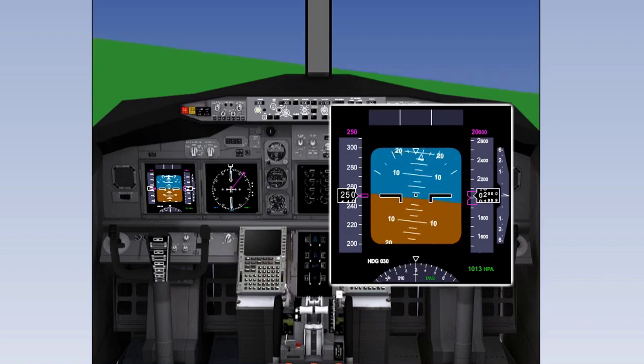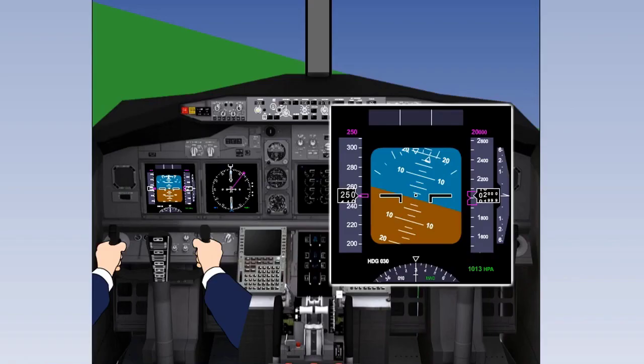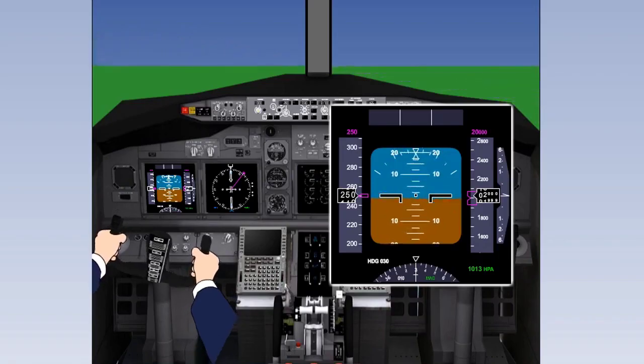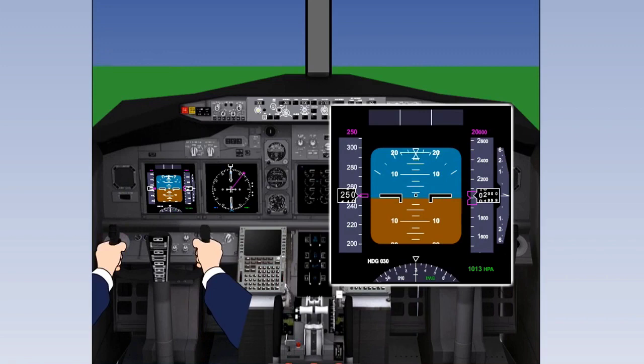In the event that a gust displaces the right wing upwards, the change in attitude will be noticed by you. By looking at your reference value, you will be able to mentally assess the rate and magnitude of the displacement. That will then allow you to mentally calculate the correction required to bring the aircraft back to wings level, and apply that correction to the controls. Having made the correction, you can see the aeroplane moving back towards wings level.